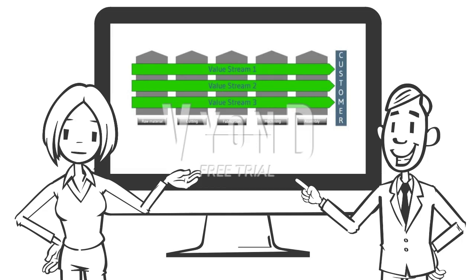Lean layouts are more likely to combine processes horizontally across the factory, compared to vertical process departments like silos in a traditional facility layout. With a lean layout, different machines tend to be grouped by product families, a group of products that passes through common processes or equipment and they have similar work content. As the processes are connected in a lean layout, much less material handling is required.